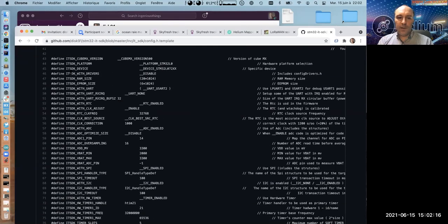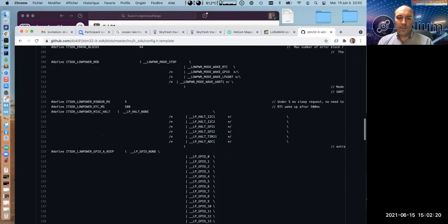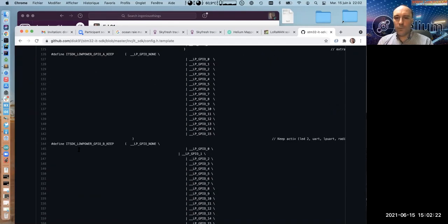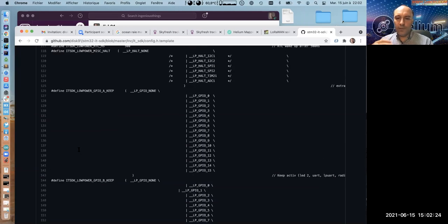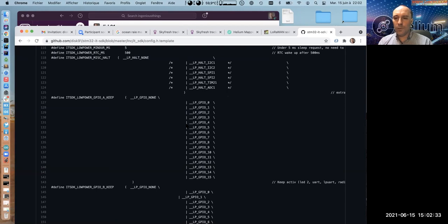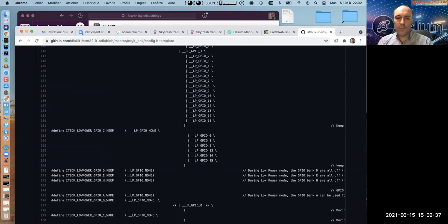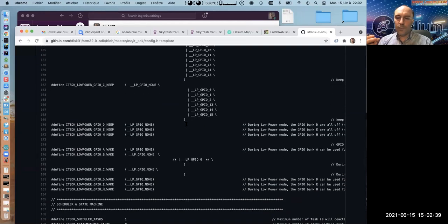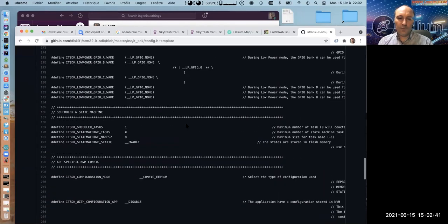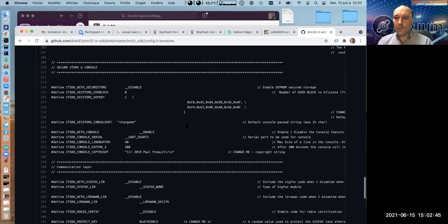So you can activate or deactivate all the features with that, for example defines if you want to have deep sleep. You decide what sub-modules you want to enable or disable, the GPIOs you want to switch off or keep, the different GPIOs that will wake up your system, and so on. You do all this configuration, and that's it.